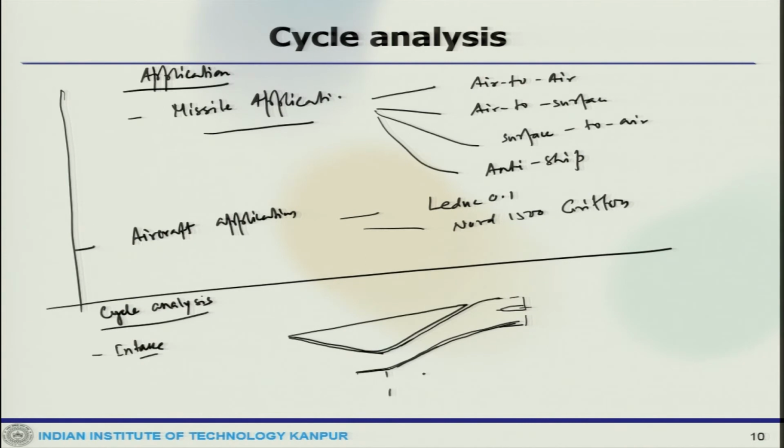So, here you have internal compression, here you have external compression, where you can see there could be shock waves, oblique shock, and there could be a lot of cross shocks which will form here like this. So, this intake module is quite important in the sense this does not have any rotating part. So, the intake actually does the compression process for this.